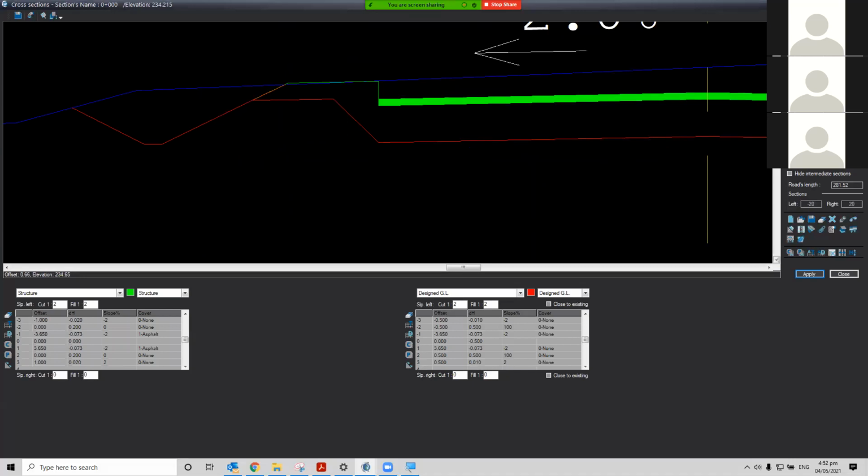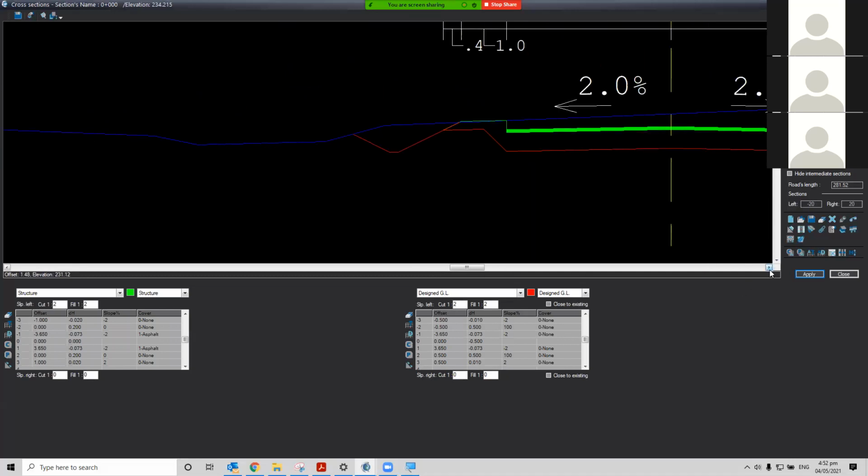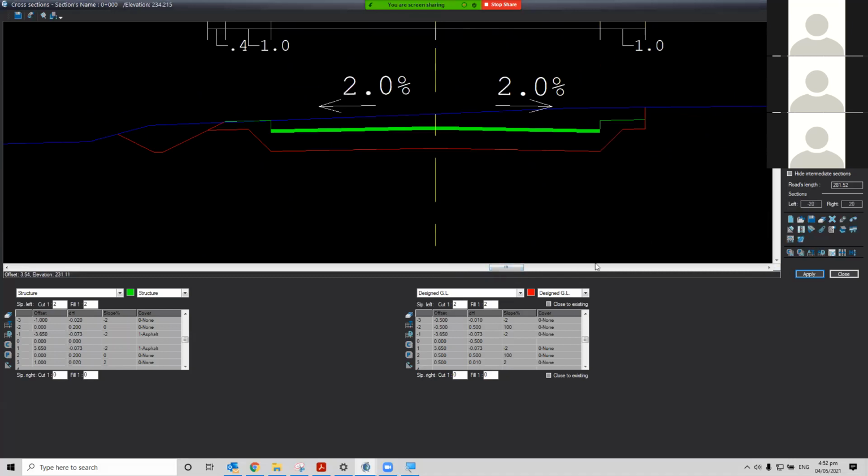Okay. All right. On the right you are perfect, because on the right you are draining into, actually what we have to do, some kind of a collector drain here on the road, and put an underground drainage pipeline. At the end of the sidewalk. Otherwise the water will... somewhere here. Yeah. But let's continue.